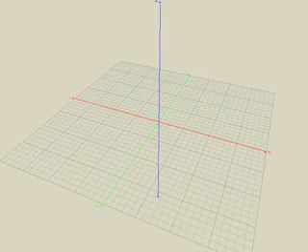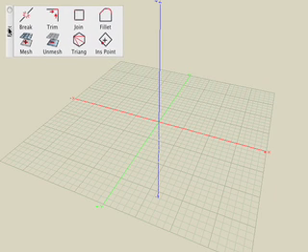In this tutorial, we'll be covering the line editing tools in bonzai3d. These are located in the Edit suite of icons. We have Break, Trim, Join, Fillet, and Insert Point. These are used on 2D and 3D lines only, not on solid or surface objects.